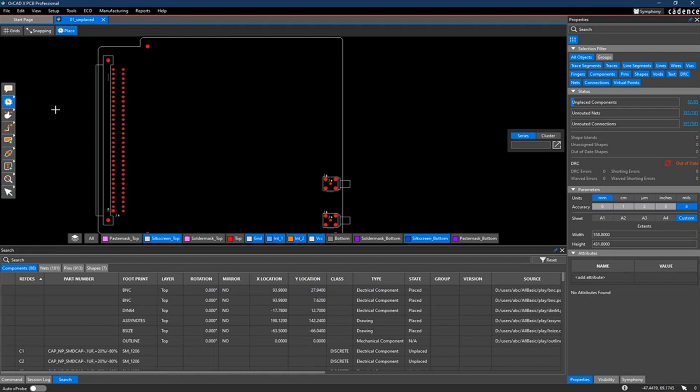For lots of these buttons, a small window opens, and you see here there's the possibility to place components by series, as I mentioned. This is basically manual placement, the old-fashioned way, and we also have a cluster possibility here. I will show this in a second. If you want to get rid of this window, because sometimes, for example for routing or sliding, this window is somehow bigger, you can go into the command and make it invisible with this button above, because it's disturbing in the canvas.